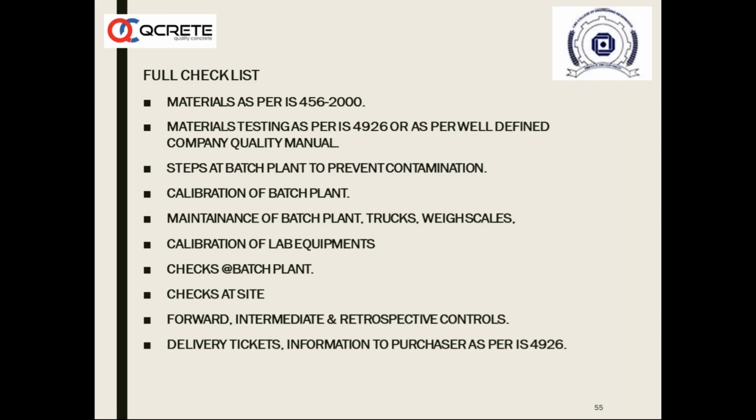What is the slump at site? What is the temperature of concrete at site? Whether the concrete is bleeding, whether the concrete is segregating, all this needs to be checked. Whether the yield is right, all these things have to be checked on site.